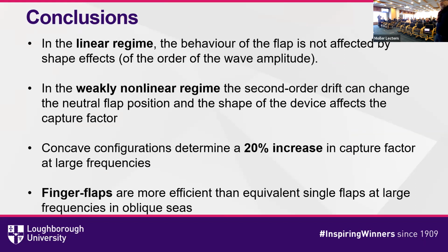That depends on the wave climate. In real life, the sea is not monochromatic, so we have a range of frequencies. I'm asking how important this increase is overall, because you are increasing capture factor at large frequencies, but we are interested in capturing overall power. It depends on where the device is. If the device is in the North Atlantic, the main resonance is around 10 seconds, which is already a relatively large period, and in the North Atlantic you get waves around that period, 7 to 10 seconds.